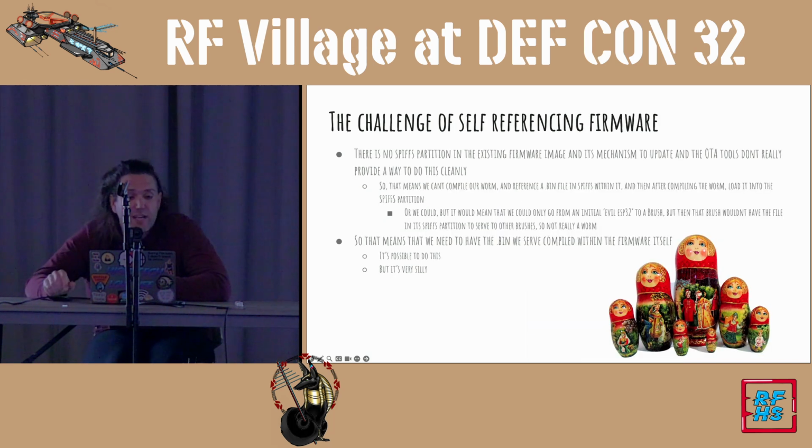So now we get into a little bit of the challenge of self-referencing firmware. At least on the existing partition table of the device itself as it comes from the factory, there's no SPIFFS partition. And essentially the SPIFFS partition is just more regularly formatted storage, such that if you have a device and it's going to display a picture on its screen or whatever, you'd usually end up putting that picture in the SPIFFS partition.